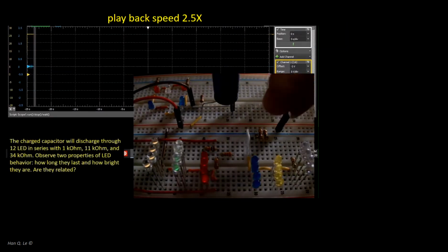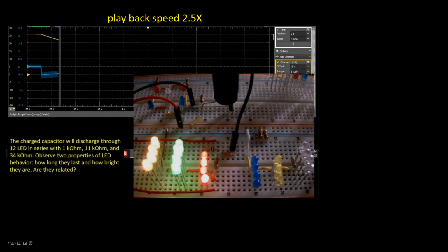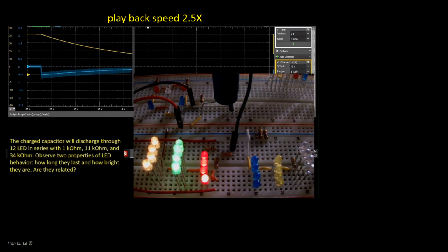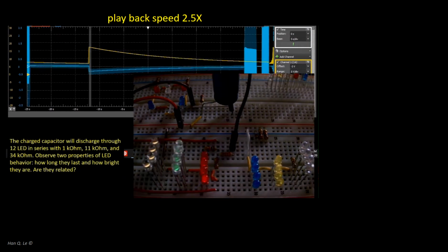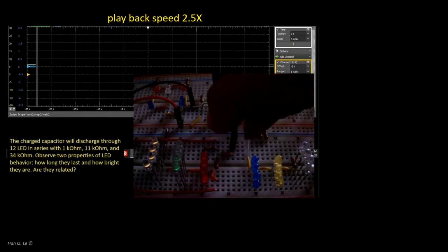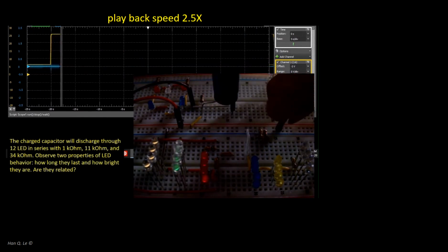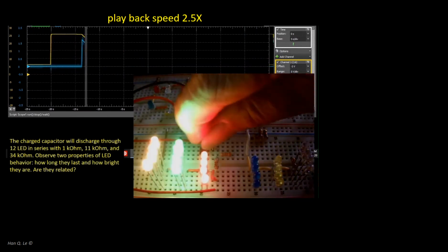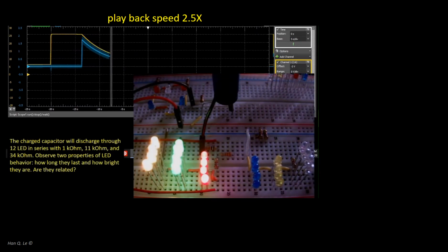The relationship between LED initial brightness and the duration of lighting is straightforward. It is a trade-off due to the constraint of the total energy. The energy of each discharge is the same. Hence, if the energy is released fast, with high LED initial brightness, then the lighting is short-lived, and vice versa. This accelerated video shows the measurements of the voltage and current for the 3 cases.